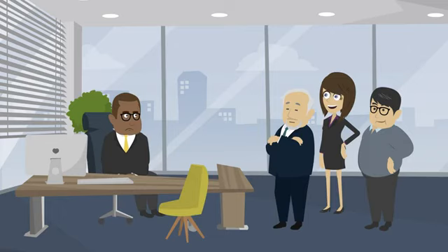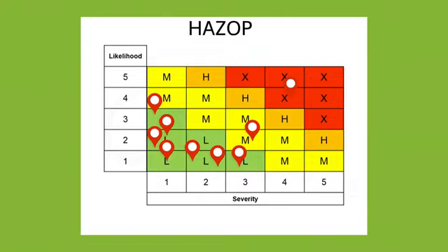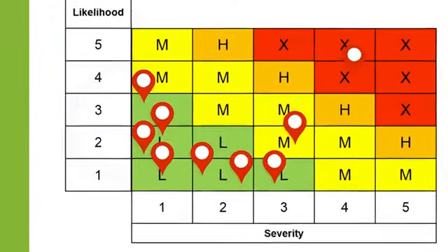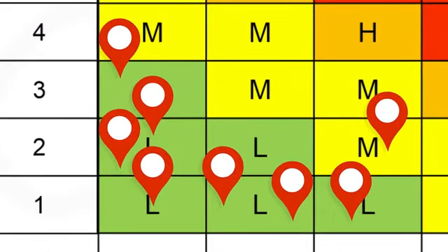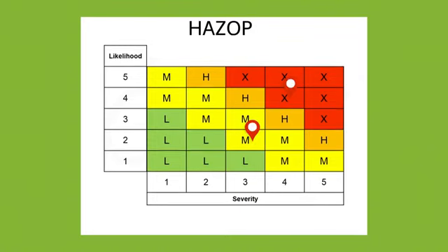But you might be wondering, what's the difference between a HAZOP and a LOPA? As we learned last chapter, in the HAZOP, a team of experts exhaustively analyze all failure modes in a process. Most failure modes are either benign or have low severity consequences, given that most failures are designed to fail in a safe state. However, there are unavoidable failures which could result in high severity consequences, like overpressure of equipment. These higher severity scenarios merit more attention.